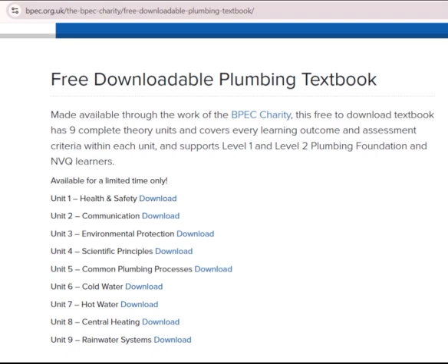B. Fully pumped, 3 x 2-port valves, S-plan Plus system using a sealed system boiler. The S-plan Plus system was designed as a result of a change in the building regulations Approved Document L1, which states that all dwellings must be zoned between the living space and the sleeping space to give individual time and temperature control across these zones. Here, the upstairs heating circuit. The S-plan Plus with sealed system boiler.